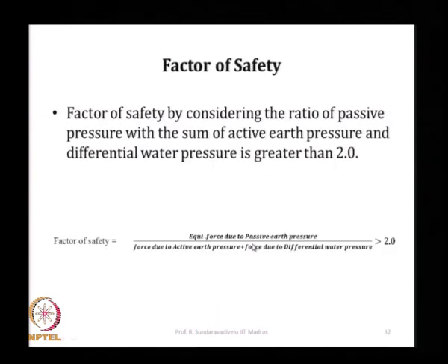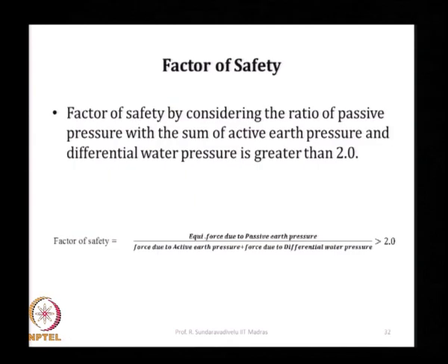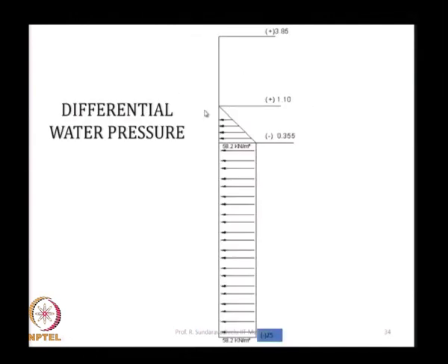So, you are given the water level here. We have assumed 0.3 meter. There is a procedure to calculate the water level on the seaside depending on the drainage condition. So, using that we have calculated the differential water level is about 1.455 meters. Using that you can calculate the differential water pressure. 58.2 is given here because 1.455 will give 14.55 kilonewton per meter square, but you have to multiply by 4 meters. Is it clear? Why 4 meters?